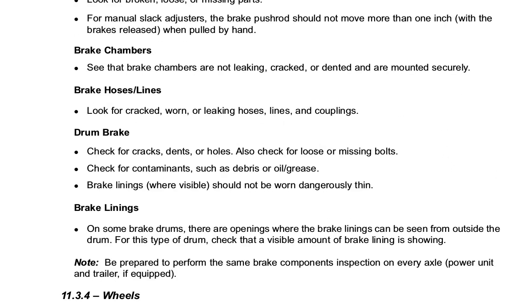Brake chambers. See that the brake chambers are not leaking, cracked, or dented and are mounted securely. Brake hoses and lines. Look for cracked, worn, or leaking hoses, lines, and couplings. Drum brake. Check for cracks, dents, or holes. Also check for loose or missing bolts. Check for contaminants such as debris or oil and grease. Brake linings, where visible, should not be worn dangerously thin.